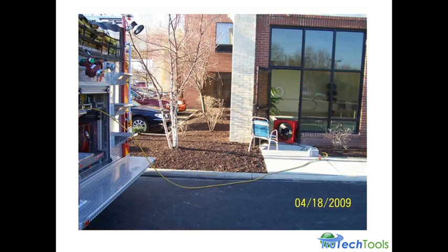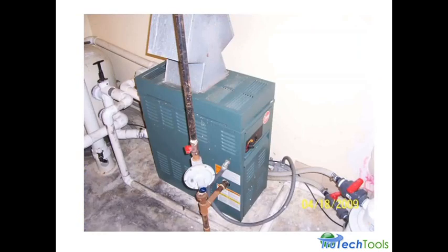They go into the hotel pool room, and this is actually a boiler in there that's pouring CO into the place. They throw a fan in and start ventilating the CO out of the space. They got to get the CO out of the building. They eventually get the CO down far enough, and they go in and secure the boiler. You can see they shut the gas off there. They tested the space, got it down below 9 parts per million, and then we went in to do some testing and actually see what was wrong.